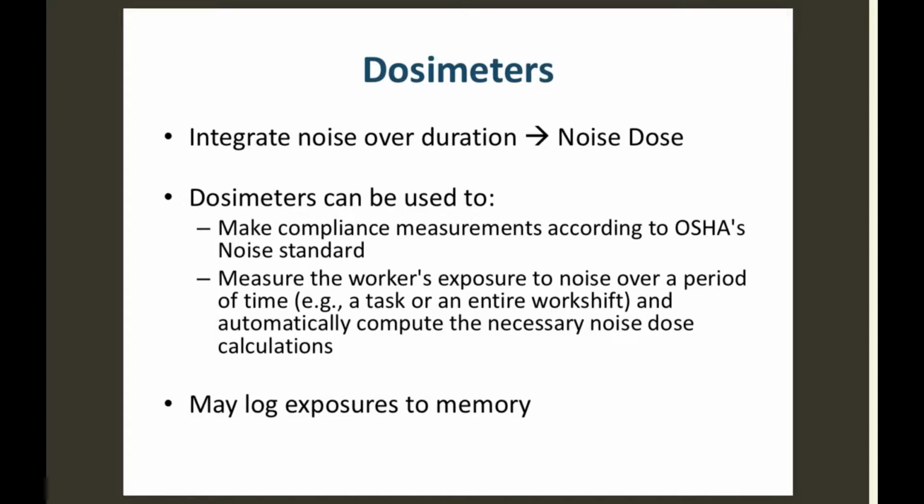But what are the variables here? When we measure sound, we have a couple of things we have to be concerned about, in terms of what we're measuring. If we're taking measurements of human exposure, what setting do we have to have on here? A scale. We want to make sure it's on the A scale. Probably want a slow response.